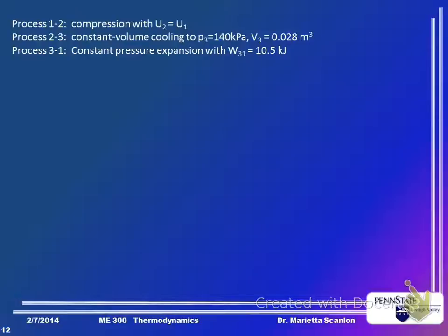I am going to pull back to the previous slides that I skipped today. One of the things I introduced was the concept of constant volume specific heat, C sub V. If you didn't look at the notes, I suggest you go back and look at them. Basically, delta U is equal to CV delta T. I'm bringing that up because if U is constant, that means T is constant. U depends on temperature. So the equation I want you to use here for process 1 to 2 is T equals a constant, so T1 equals T2. V equals a constant, P equals a constant.